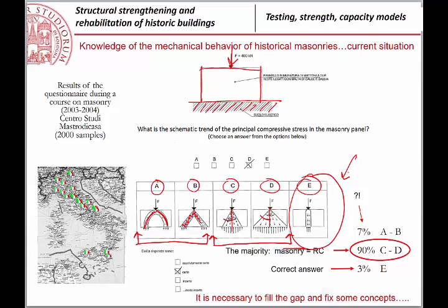Bad quality of the mortar, bad quality very often of the assembly of the blocks, that is, blocks which are not assembled regularly. And if these two things occur, bad quality of the mortar and bad assembly, the masonry is not able to distribute the loading. That is, the loading is just going almost straight from the point of application to the foundation.